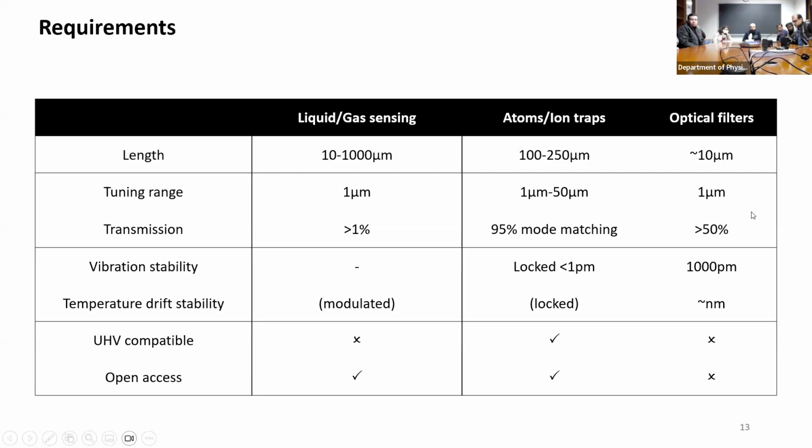If you have a very faint signal, if you attenuate most of it, then there's no point in having a filter like that. I will talk about stability, but you may need high picometer level stability, and you may need high vacuum compatibility. So there's a lot of requirements, but my project was about prototyping it. Just make it once, see if it works, what are the challenges, and then see if we can make a product out of it, but depending on the customer requirements.